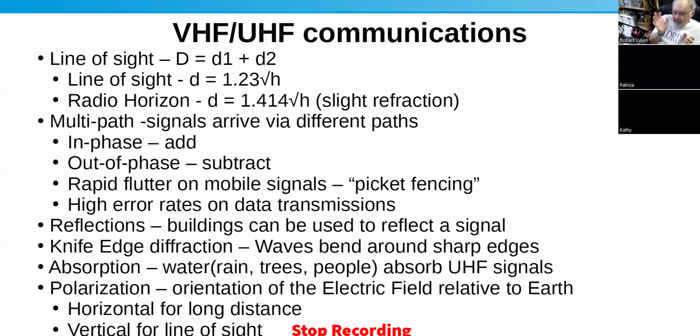If you hold it upright, it's going to be vertical. So when you're talking straight line of sight type communications, polarization makes a big difference.